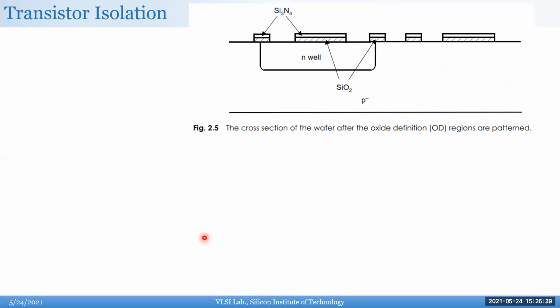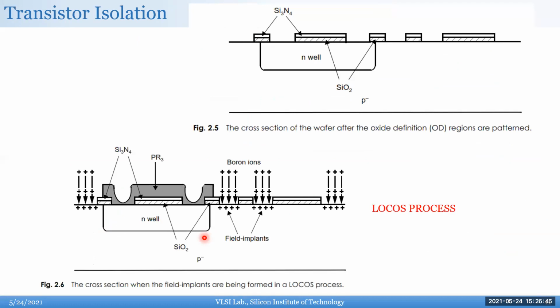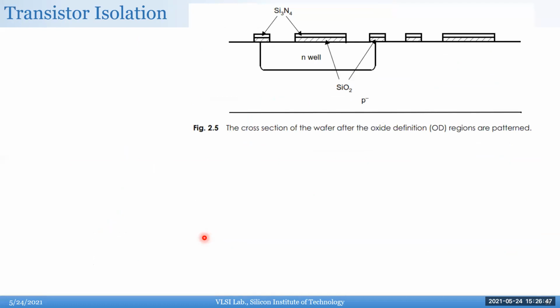Okay, so transistor isolation. Now this is a monolithic wafer, right? So you have one wafer, and it's not insulating. The p-type substrate is actually conducting. Now it can be highly conductive, or the conduction can be small, but it is still conductive.